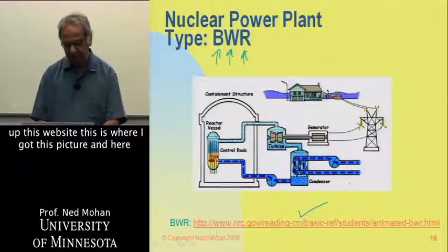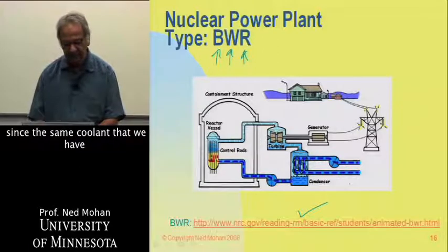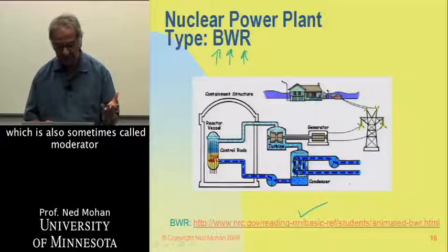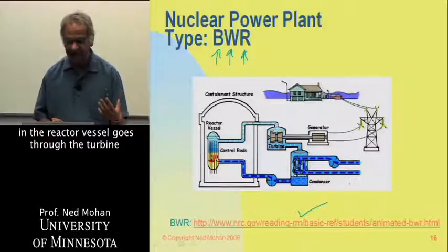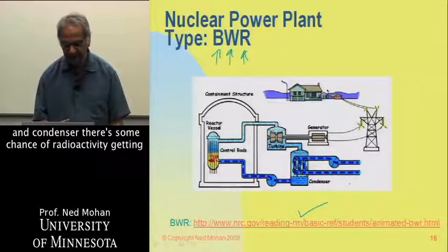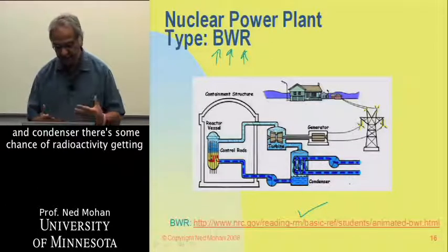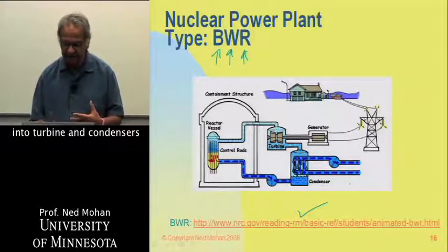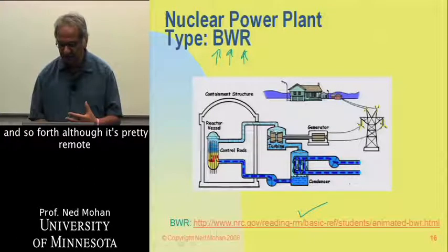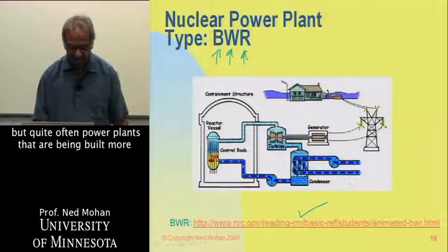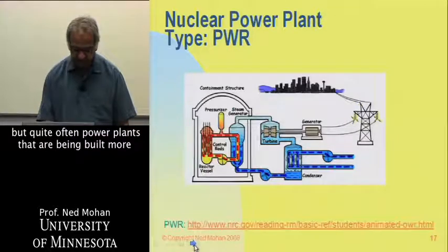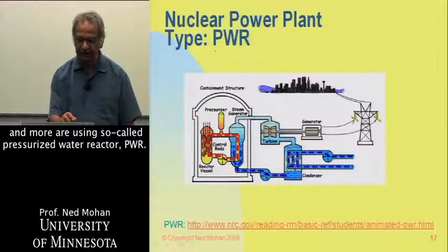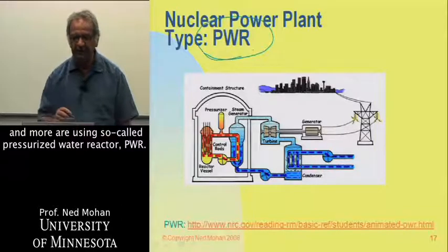And here, since the same coolant that we have, which is also sometimes called moderator, in the reactor vessel goes to the turbine and condenser, there's some chance of radioactivity getting into turbine and condensers and so forth, although it's pretty remote, but quite often the power plants that are being built more and more are using so-called pressurized water reactor, PWR.